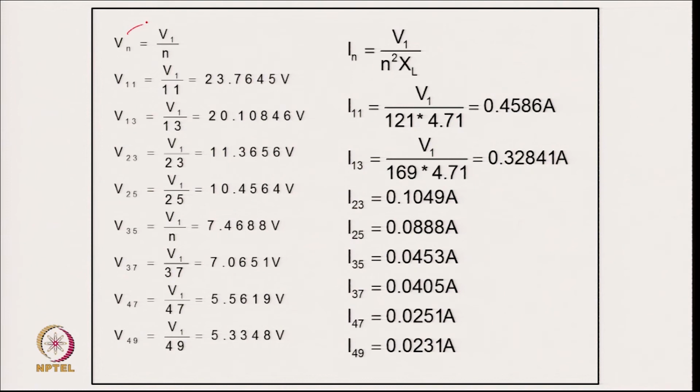Now, coming to calculating the harmonics, here we will be getting the harmonics, because it is a 12 pulse converter. So, we will get voltage harmonics as fundamental divided by order of harmonics. So, with this relation we will get 11th, 13th, 23rd, because these are the 12 pulse converter. So, you will have 12n plus minus 1 harmonics in the voltage at the input, other will cancel out.